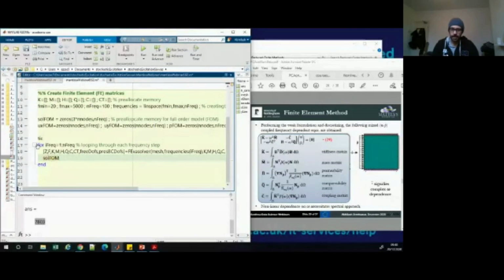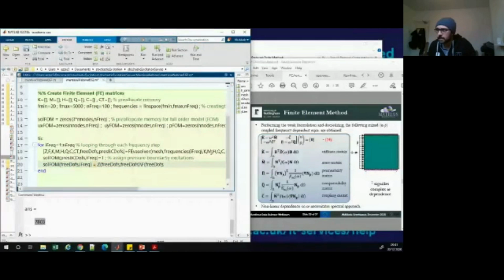Of course, this is a constrained PDE, spatially constrained. We assign it some boundary conditions here. Don't worry, it's not too important what happens. I just do it to be complete. So here we assign pressure boundary conditions, boundary excitation, I should say. And finally, we solve the problem. Solving the problem basically says that we're solving for U and P, that is, we're inverting this matrix to solve only for the unconstrained dimensions. Perfect. So solving the full order model.